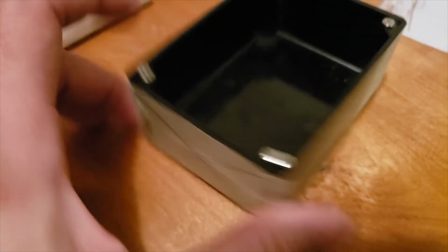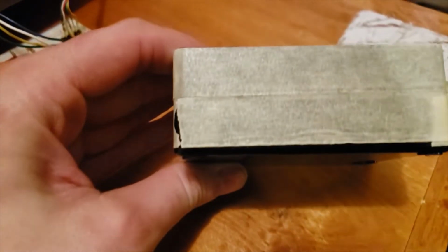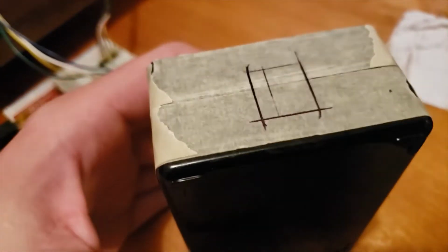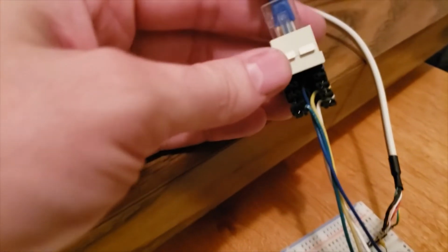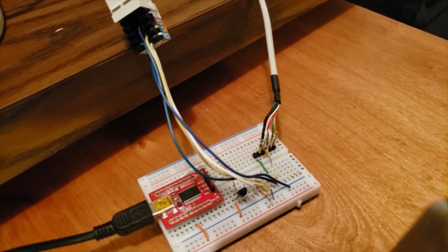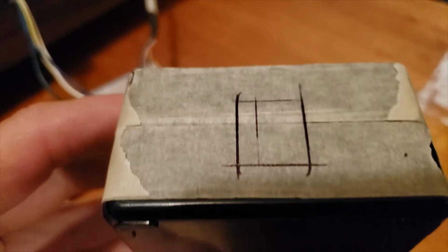So some of the things that I like to do when I'm trying to lay out a project box is I actually wrap it in tape. This allows me to be able to draw on it and get an idea of how I want things laid out without making it too permanent. So this right here I laid out specifically to house that connector. I decided rather than buying a panel one that would theoretically mount better, I got a whole bunch of these just lying around. I'm just going to cut a nice little square out and put it into place right there.